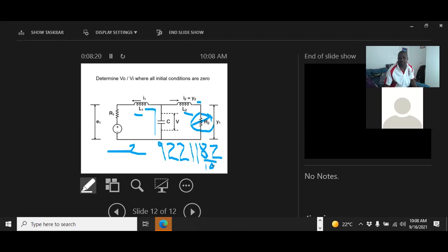And then from there, I ask you to apply DC and increase this in steps of 10 and plot the gain for each value. Apply AC and then plot the gain for each value. That's all. And then from there, you make a table. This is DC, V in, V out, again V in, V out. And without this thing, put a multimeter to measure resistance, measure there, and measure here, and work out the gain. So those are the things.